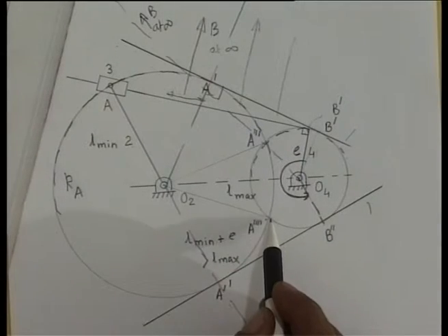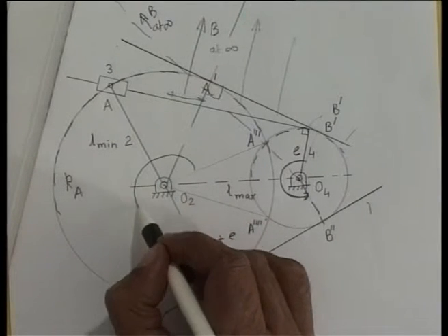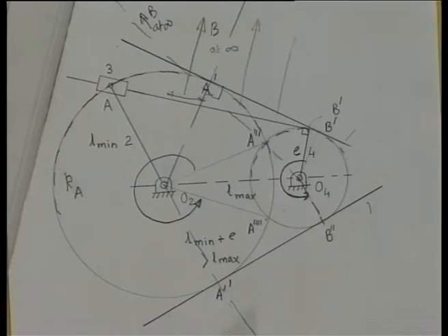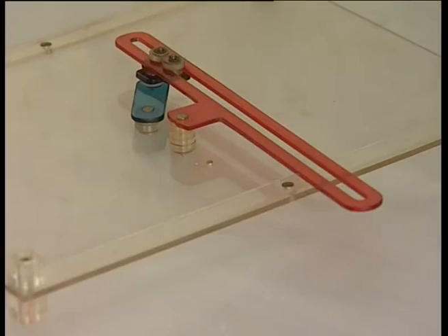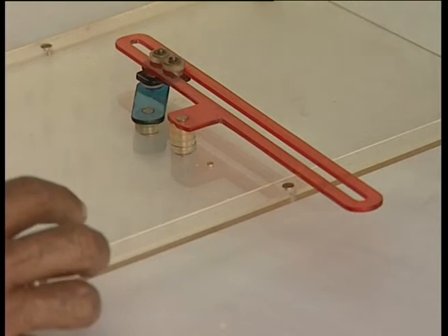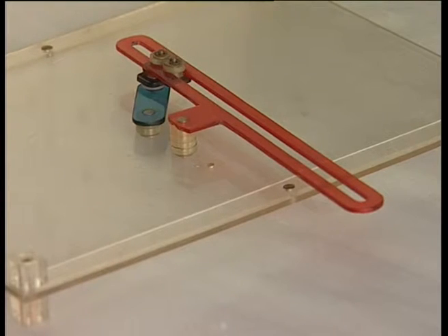Same will be true for this point of intersection, and link 2 oscillates through this large angle between its extreme positions. Just now we have seen a very large angle of oscillations of the input and output links of a 3R1P mechanism, which is of non-Grashof type.